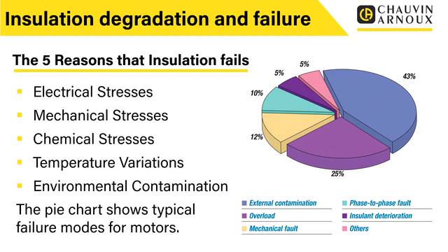So again, there are a lot of reasons why insulation can fail. And obviously, common sense dictates that keeping your motor dust-free, dry, clean, away from any oils or contaminants or coolants and things like that, all of those things are obviously good practice if you want to see your insulation last and a long life for your motor. So again, in any preventative maintenance system, we try to keep away from that.